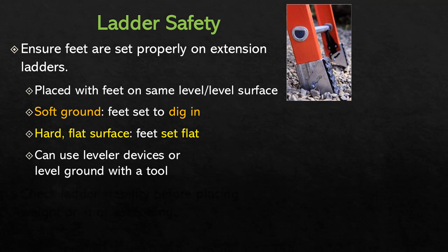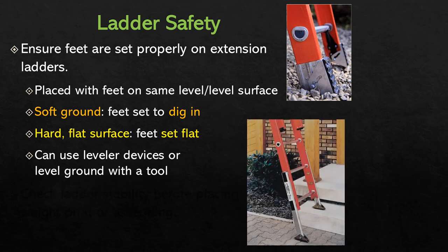If the ladder is on a hard, flat surface, you want to set the feet flat on it. Again, that's exactly as you would imagine. Most ladders have a couple different settings on them where you can set them flat or you can set them to actually dig into something. But regardless, you need to make sure that you use a leveler device or some other tool to ensure that the ladder is set right, or the ground is built up in such a way that the ladder goes straight up and the feet are level.